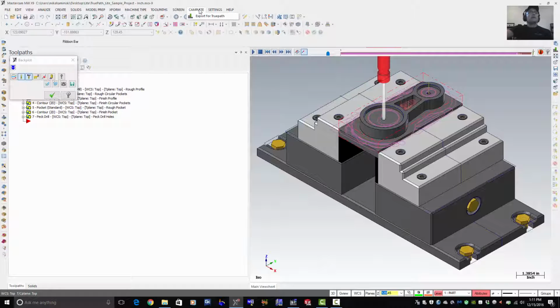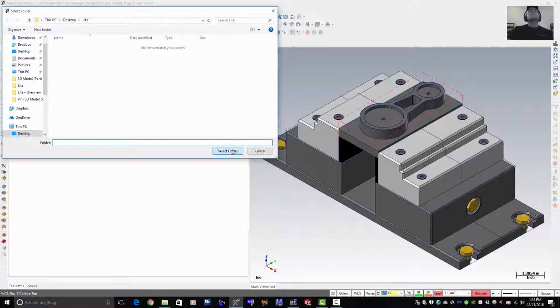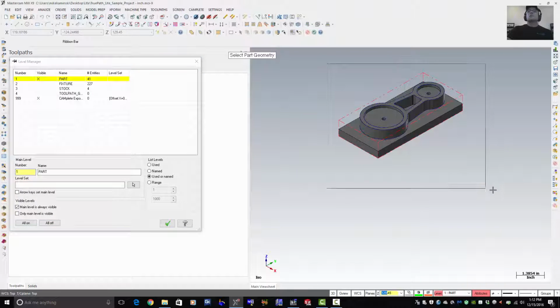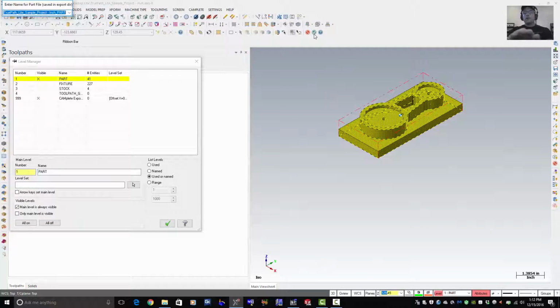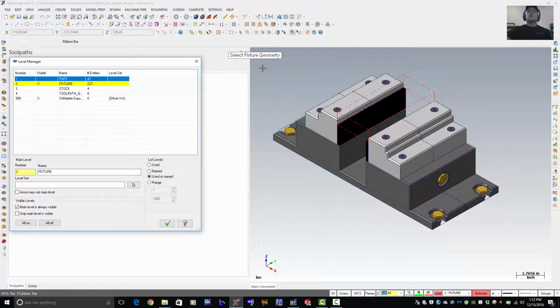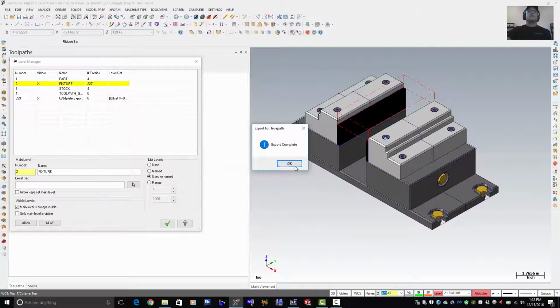We have a plugin available for our advanced application for 5-axis. I'm going to use that same application so I can grab the fixture, part, and tooling and just simply select one file and have it bring it all into the project. Select my part first and provide a name. Select my geometry for my fixture second. Provide a name.